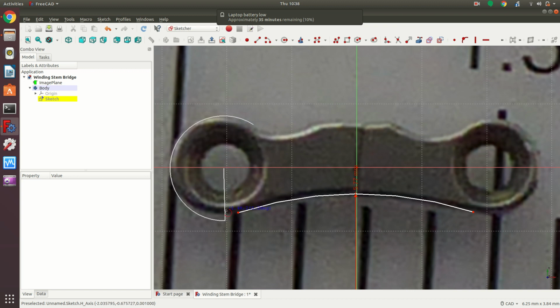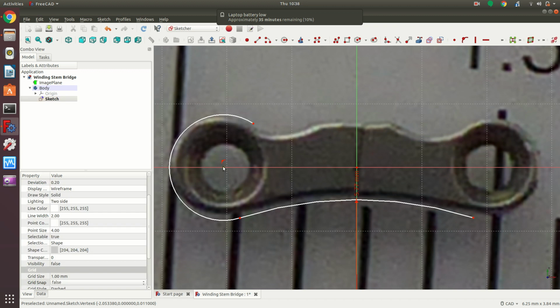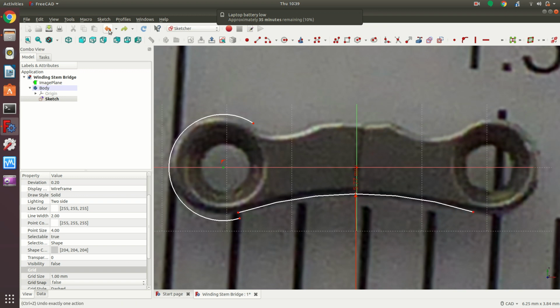And we go around, and we can already see we're totally off. But I'm going to make it join the dot here. Okay, so what that does, it moves this line. Now we have to move the center of the circle. Actually, I'm going to undo this because I want to fix that line. I know that line is correct. I'm going to fix this totally. So I can't move it anymore. I'm going to fix the length of it.